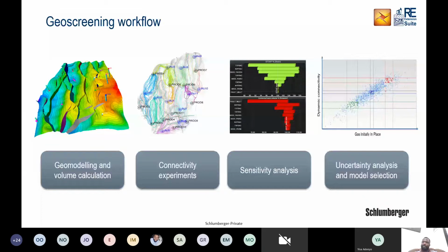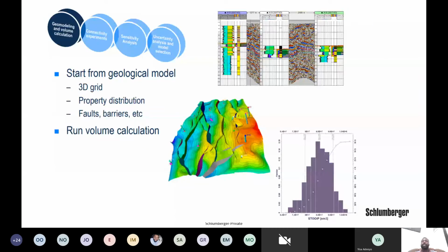We start with geological modeling. You need to have in Petrel a geological model built from the logs, seismic, physics models, petrophysical models, up to the volume calculation. The reason is that if you have any uncertainty, for example, in your sand proportion, in the top of your channels, or in the extension using variograms to your sand bodies, you can use uncertainties to address and quantify those parameters.